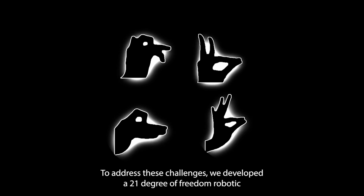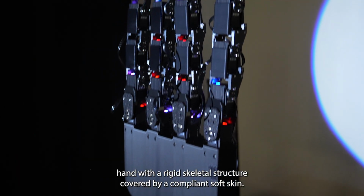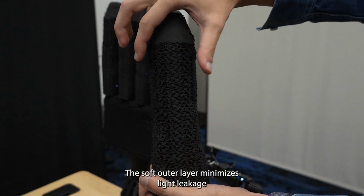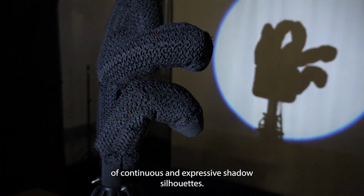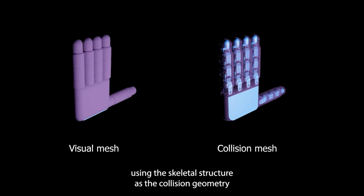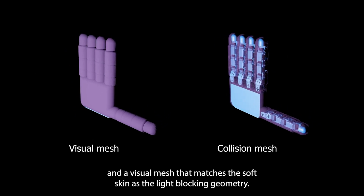To address these challenges, we developed a 21 degree of freedom robotic hand with a rigid skeletal structure covered by a compliant soft skin. The soft outer layer minimizes light leakage while preserving dexterous finger motion, enabling the creation of continuous and expressive shadow silhouettes. We model our hand in simulation using the skeletal structure as the collision geometry and a visual mesh that matches the soft skin as the light-blocking geometry.